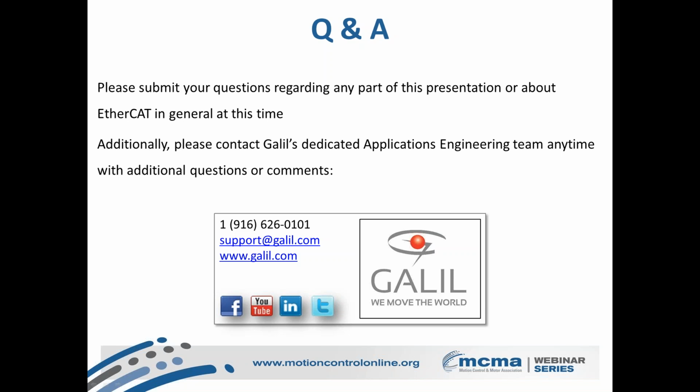One of the engineers I work with likes to put it as determinism and wireless don't go in the same sentence. First off, using EtherCAT with any of the standard Ethernet hubs, switches, anything like that, wireless or not, is a non-starter. However, the problem with determinism and wireless communication is that it's tough to diagnose if there are breakdowns in communications. If an EtherCAT master sends out a data packet to slaves over wireless and it doesn't get there, how did the slaves know that they were supposed to get something?